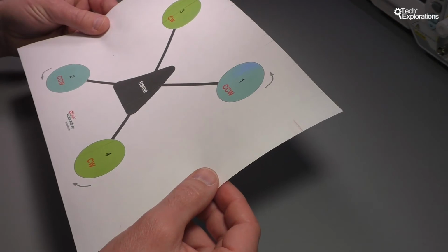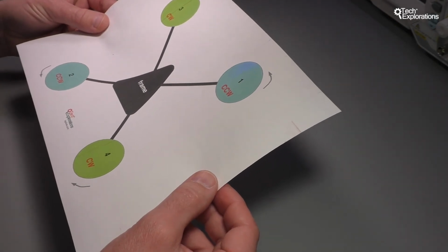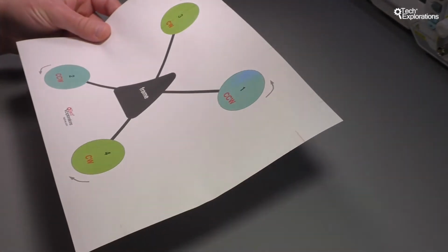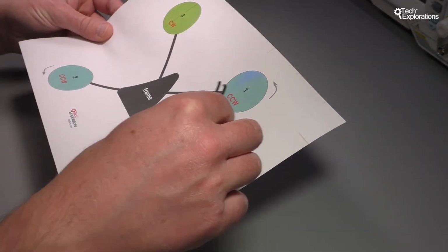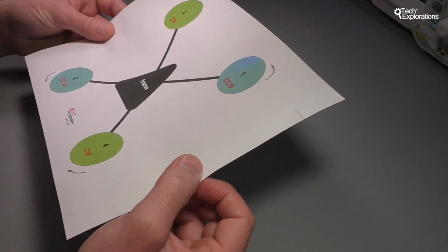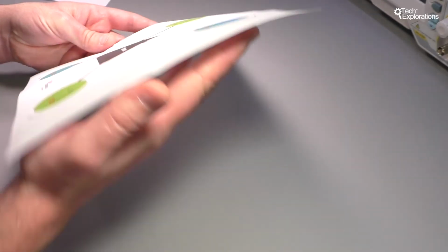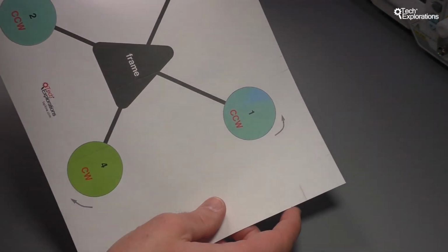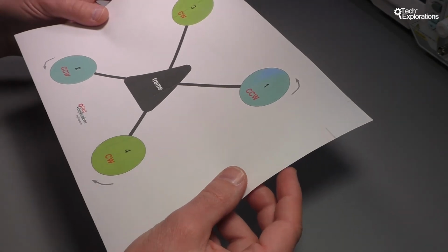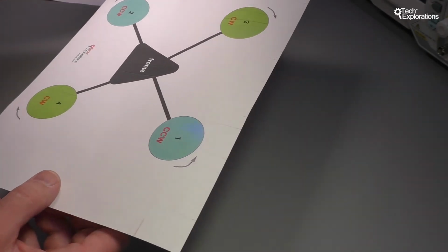And similarly, if you want to get your quadcopter to bank towards the left like this, then you need to increase the speed of motors 1 and 4. That would create thrust on these motors and push the quadcopter to bank towards the left, and similarly towards the right. Another thing that you can do is get your quadcopter to just rotate on its vertical axis